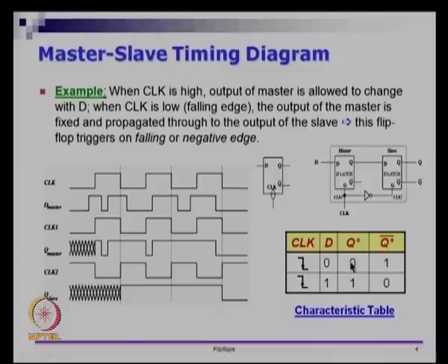So it is just the data input, only that we can now forget the fact that it is actually made of 2 flip flops and there is some careful connection inside and so on. We can now go up one level of abstraction and start using this circuit as a D flip flop as it is. I will treat it as a black box, and I will not show the connections later on. Only when I need it will I show it; till then I will assume that a D flip flop is just this external black box. I will assume that you understand what the internal details are, alright.